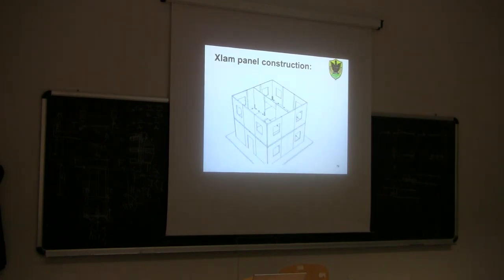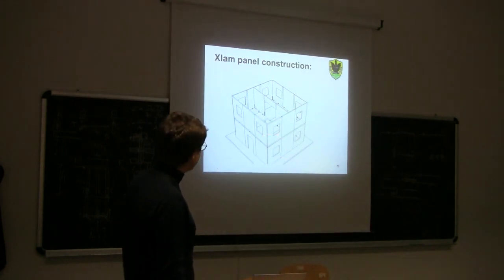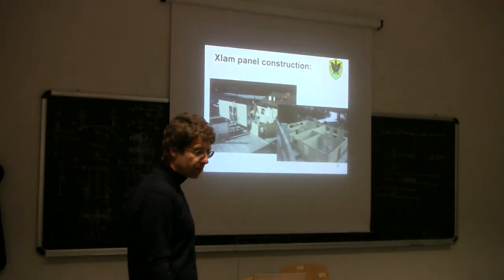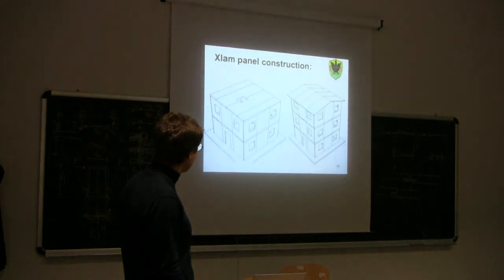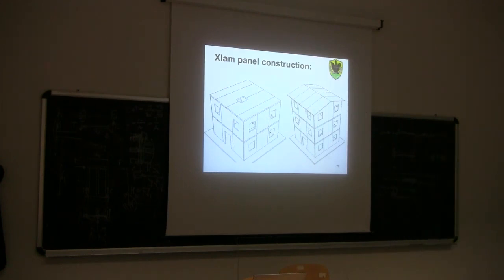And then we proceed by, again, placing, you see, on top of the floor. So again, this is what we called before, another example of platform construction. Because you see that on top of the floor, we place other walls. And then another floor, and then another wall, and so on. So the floor panels are squashed between the supporting wall and the wall on top of the floor. So in the end we get, as you can see, a very strong structure by using this kind of system.